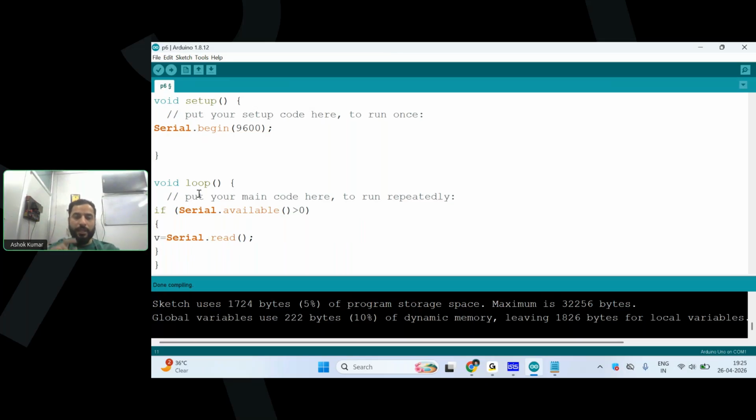Now, as I mentioned, whenever we use serial communication like GSM, GPS, Bluetooth, Wi-Fi, whatever data you are transmitting is always in the form of characters. So let's define the type of this V as char. Like the data type integer, here we have a data type char. Correct?